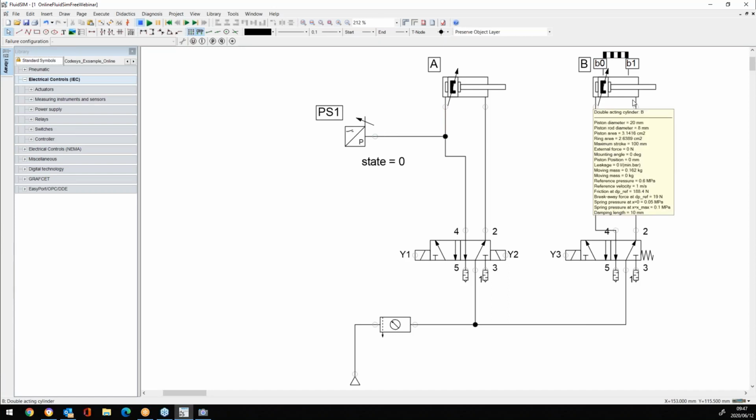All right, what I'm going to do is build the electropneumatic circuit with you. I've changed my valve already to a double solenoid valve. That means, like he said, an MCV, a memory control valve. It's a memory valve with two solenoids. I've labeled the solenoids Y1 and Y2. Then my drilling apparatus, I've made it Y3. I've also added my speed control into my circuit so that it will go forward slowly.